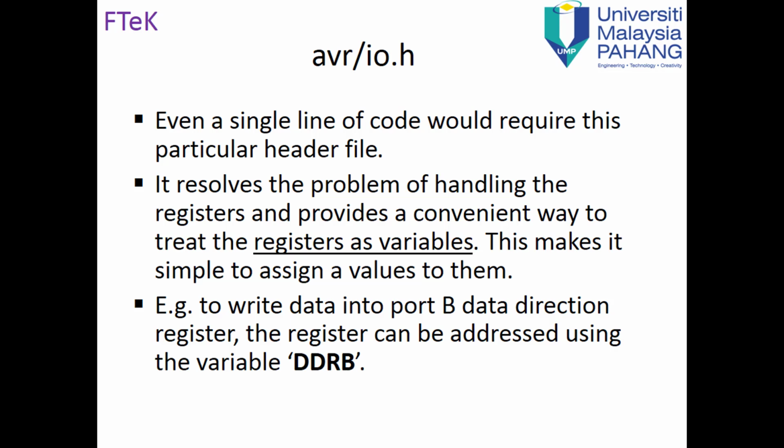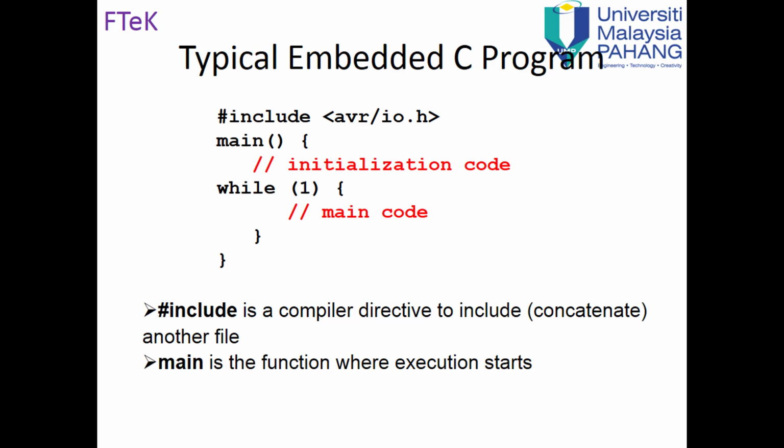So it resolves the problem of handling the registers and provides a convenient way to treat the registers as variables. So from now on, no need to worry about the registers. So register 1, register 20, whatever, just use a variable. You can use many types of data, and you can write your program similarly to what you do when dealing with your PC, when you write a program for your PC.